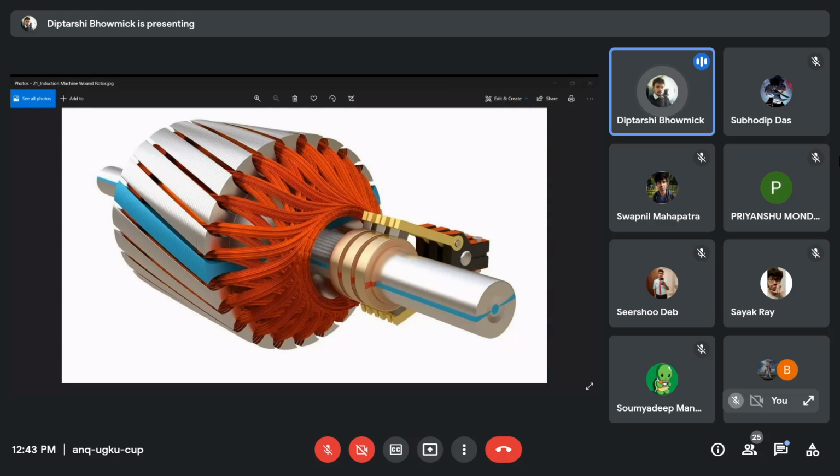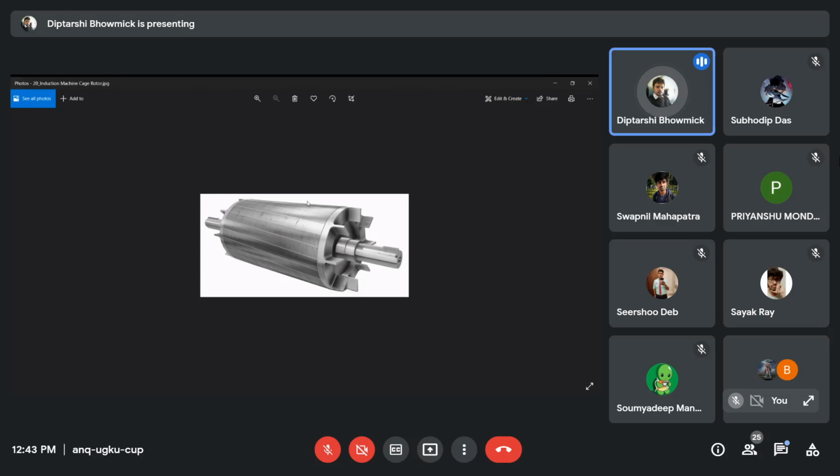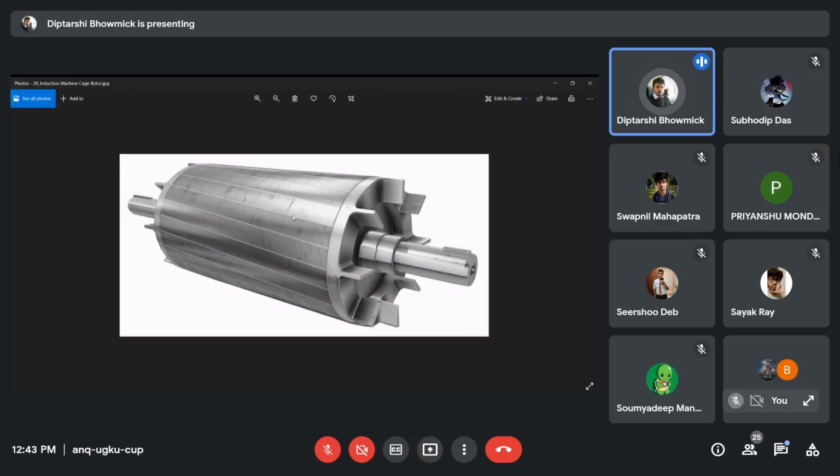Well, so the rotor diameter is 9.1 centimeter. Number of slots, you have to count the number of slots. How can you count it? In our laboratory, we have a squirrel cage machine, so your rotor will look like this. You have to count these lines, and find the number of rotor slots. Now the slot pitch is similarly pi d by number of slots.